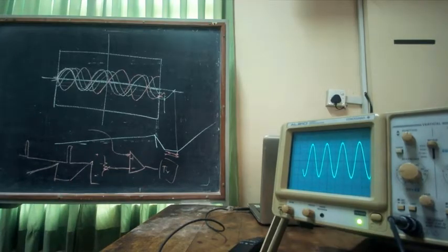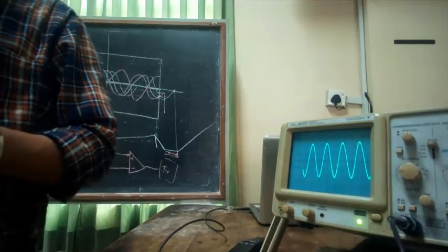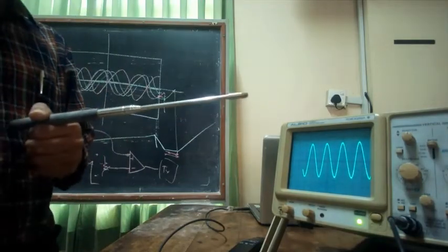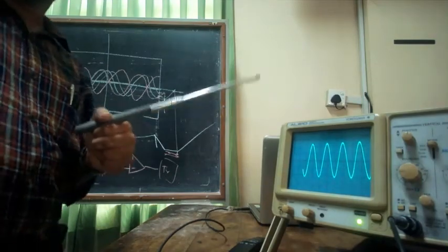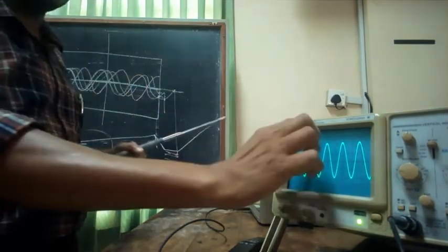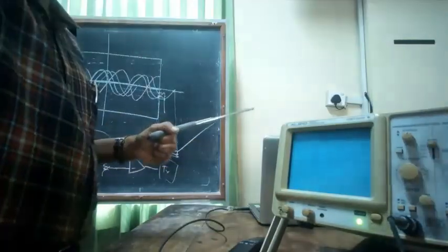Right. So that basically covers the sweeping, and triggering. Now if your signal doesn't get triggered, remember triggering means you have a stable signal. That means your trigger level is not correct. It has gone beyond your signal level. The signal is varying somewhere, and your trigger level is outside that range.